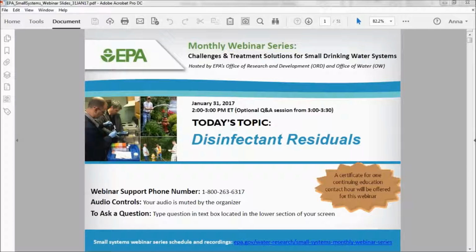At this point, there's not an EPA-approved method specifically for monochloramine residual. Systems rely, I've seen just mostly the total chlorine DPD method for total chlorine, and total chlorine will be the sum of free chlorine, monochloramine, dichloramine, trichloramine, and also any other interfering compounds. But at this point, just total chlorine, the DPD method, is probably the most commonly used field method for chlorinated systems.